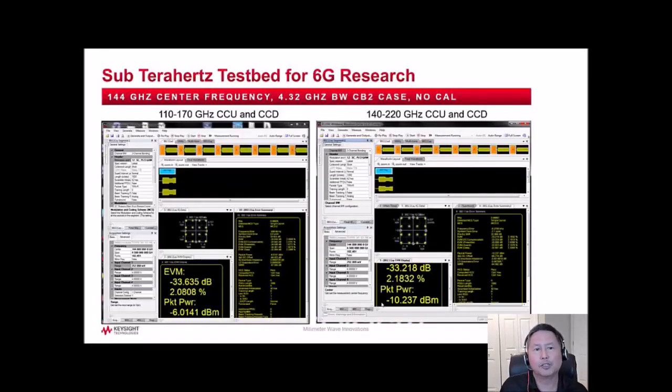Single carrier QAM measurements were performed at D-band at 144 GHz center frequency with varying modulation bandwidths. These were conducted measurements, waveguide to waveguide, without horn antennas. Since 6G waveforms are not defined, 802.11ay waveforms were used as an initial test case and as an example of an emerging millimeter wave wideband standard with optional bandwidths up to 8.64 GHz of bandwidth.